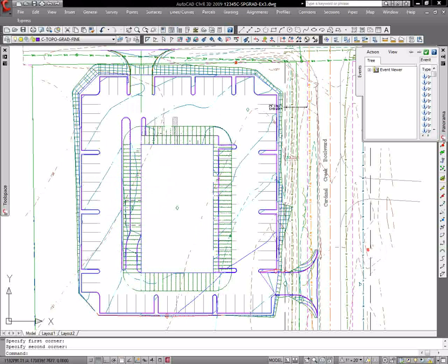First of all, we set all the grades flat across the north face of the building. We fixed up the ramping of the pavement so that we've got that at-grade pedestrian access. We also created some elevations along this area, a low point here, so that we have a way to drain this north face of the building. And finally, we applied some smoothing in some areas where the triangulation was a bit rough. So our grading model is looking really good at this point.